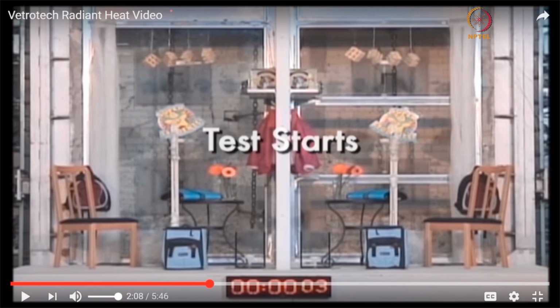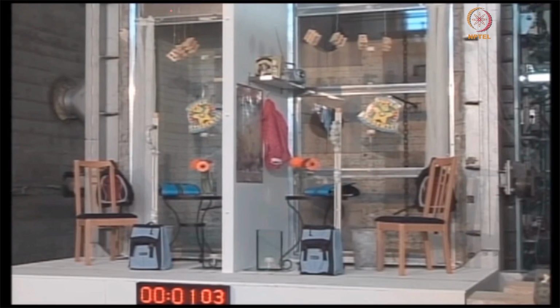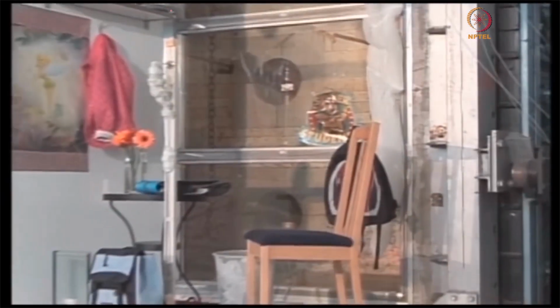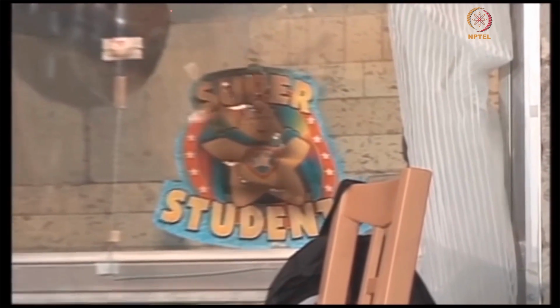On the right, we have installed a fire resistance rated EW glass, and on the left we have used an E-rated glass, which is integrity only. So you will see a combination of integrity with radiation control on one side, and a glass which has only integrity on the other side, and we have kept identical materials on both sides of the glass. Here you will get to see, in a real fire scenario, how each of these glasses behaves, and what is the consequence of the performance of this glass on the combustible materials in the vicinity of the glass.